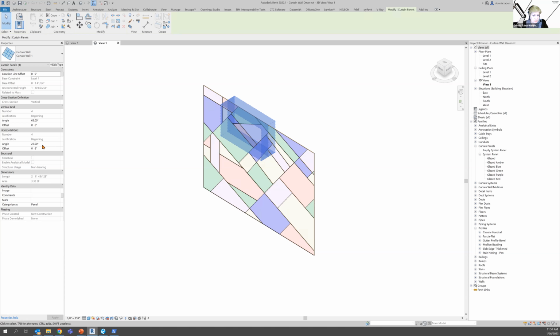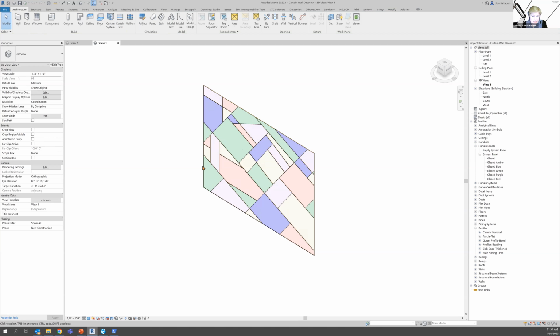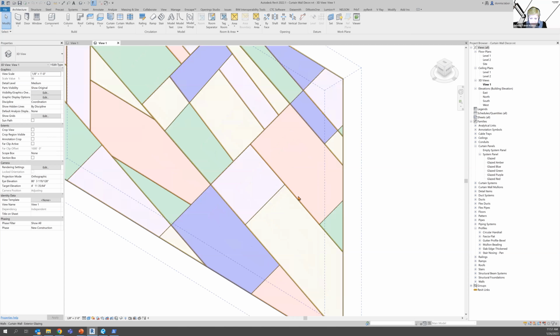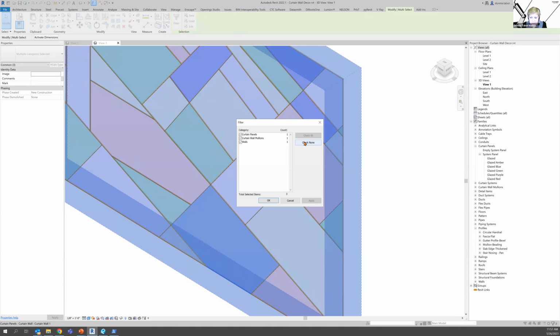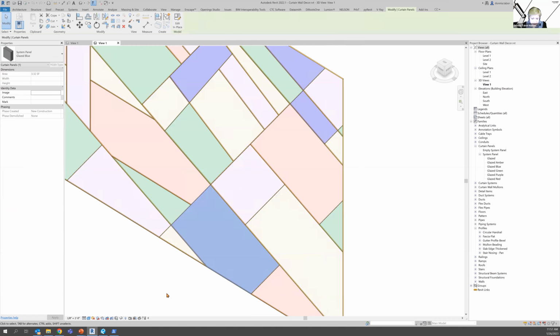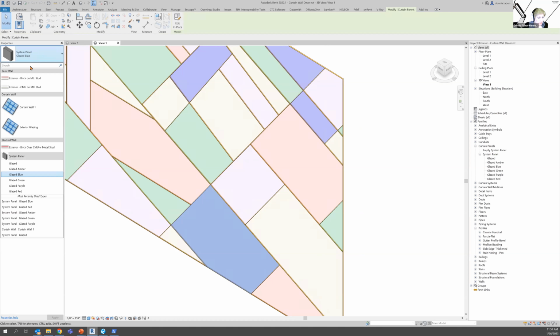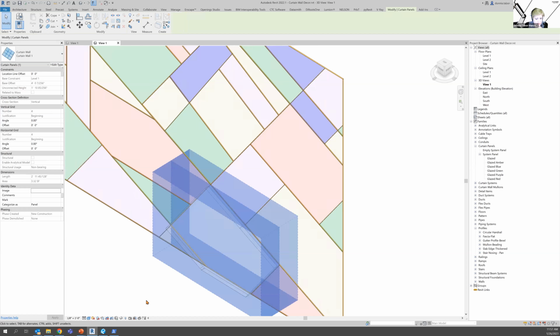So I told you could change the angles, you can. And then I went in and individually picked the panels inside that curtain wall, the curtain wall that was a panel, I picked its panel. There we go. And kept changing colors. So it would be as easy as going in here and taking, let me see if I can do this right here. Pick on this filter. Give me that panel. So it'd just be a matter of taking that panel, instead of it being glazed blue, I could turn it into a curtain wall. And now it's a curtain wall in itself. And then let's give it some mullions at 50 degrees and 30 something. And then I could put some grid lines on.